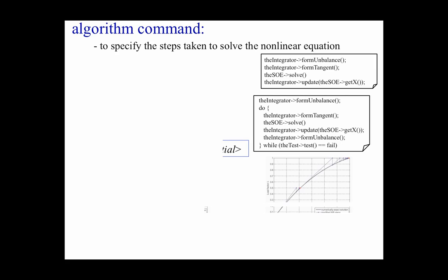That's our solution space. We don't have this nice solution space. That's why we have problems when we're trying to converge. So Newton works nicely if your system is nicely behaved. But when it starts getting kinks and all this kind of stuff, we have to switch to modified Newton.